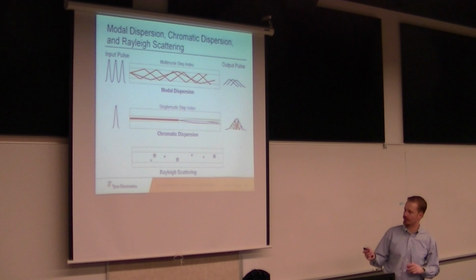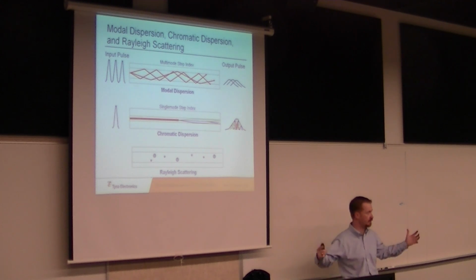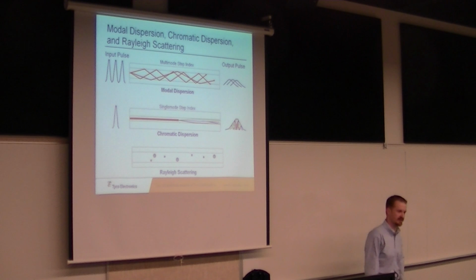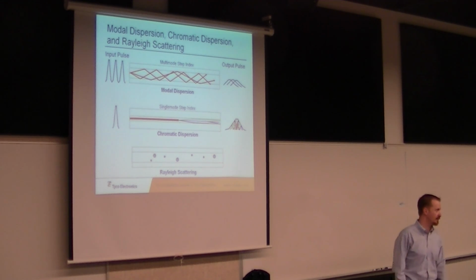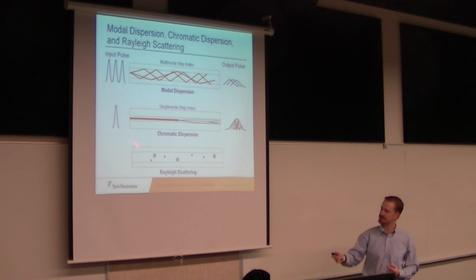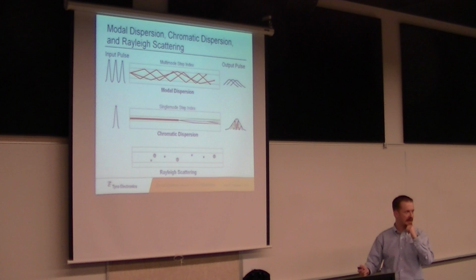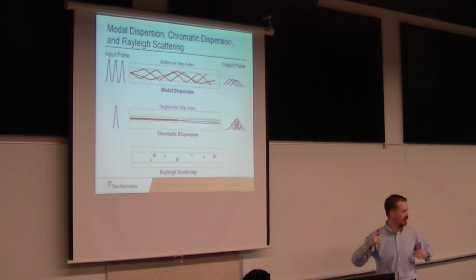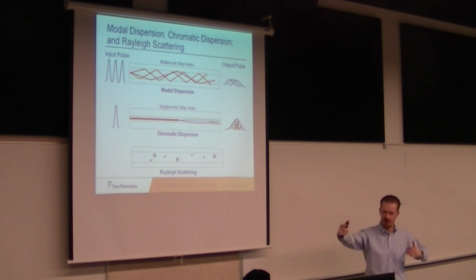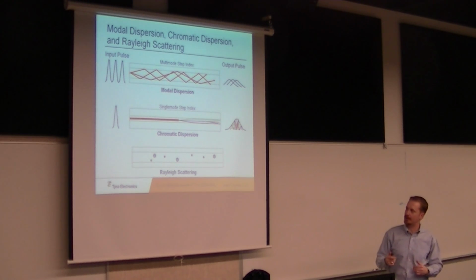These impurities are in there for a reason, and that's when you use an OTDR or any other type of test equipment that's going to tell you the length of your cable. I mean, if you run something across the Pacific Ocean, do you actually want to stand there and step it off? You can't walk across water. But you can use an OTDR to check that. Well, these imperfections here are what allow the light of an OTDR and other equipment to bounce back. And so they can get a gauge and say, okay, I'm going out 10 meters, 100 meters, 10 kilometers, 100 kilometers, whatever it is. So they're there.